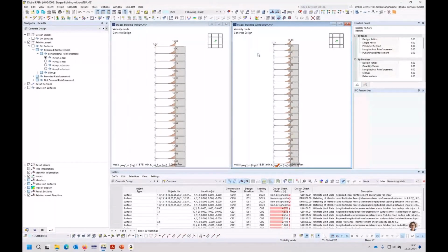And there are structures, depending on how complex or how high these structures are and how long the construction process is, where you have an influence due to long-term behavior due to creeping, where there could be a redistribution of the internal forces. Like shown for the first example, there was a quite significant change.